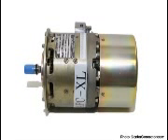As the number of loops is increased, the variation between maximum and minimum values of voltage is reduced, via figure 9-8, and the output voltage of the generator approaches the steady DC value. In figure 9-8, the number of commutator segments is increased in direct proportion to the number of loops. That is, there are 2 segments for 1 loop, 4 segments for 2 loops, and 8 segments for 4 loops.